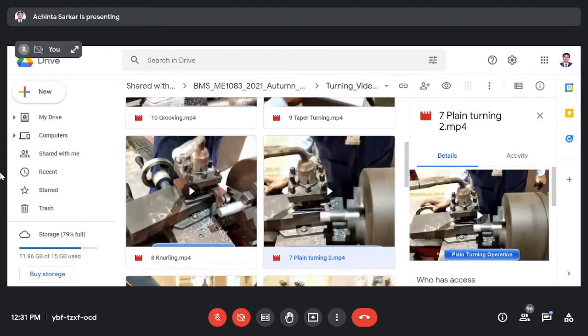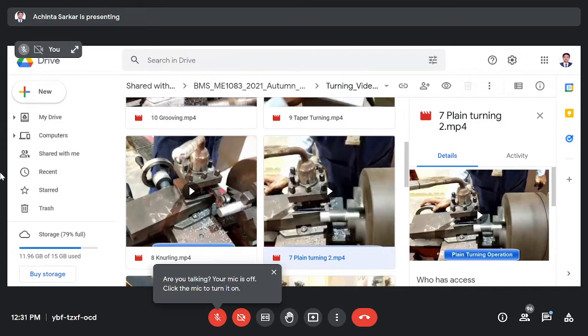And if I take more feed rate, then we are going to create a rougher surface, and again the material may deform. Unwanted deformation may occur because of that higher feed. And again, if you make the feed very less, then the productivity will also deplete. So carefully we have to justify what will be the ideal feed rate to maintain the job quality, surface finishing, as well as the appropriate productivity or efficiency of cutting. Okay. So the feed is important.